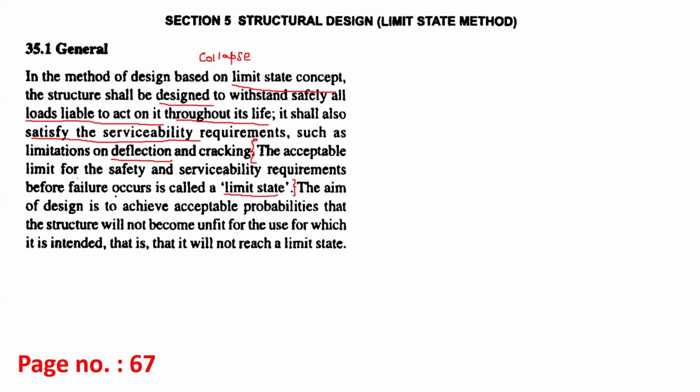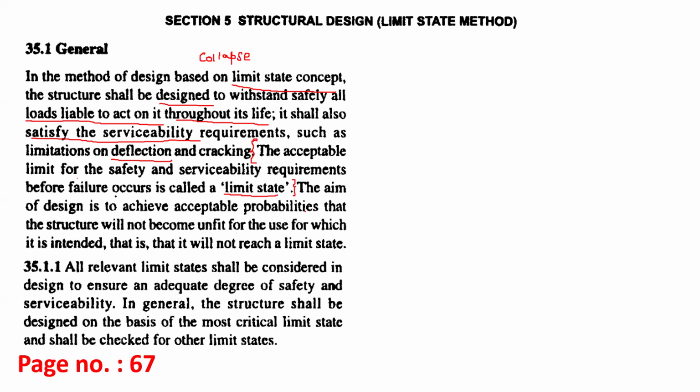Both, that is safety and serviceability. The aim of design is to achieve acceptable probabilities that the structure will not become unfit for the use for which it is intended. That is, that it will not reach a limit state. Means the loads coming on it should be less than resistance and deflection occurring should be less than the allowable deflection.